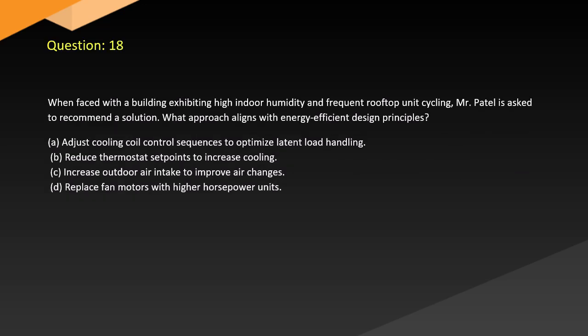Question 18. When faced with a building exhibiting high indoor humidity and frequent rooftop unit cycling, Mr. Patel is asked to recommend a solution. What approach aligns with energy-efficient design principles? A. Adjust cooling coil control sequences to optimize latent load handling. B. Reduce thermostat set points to increase cooling. C. Increase outdoor air intake to improve air changes. D. Replace fan motors with higher horsepower units.